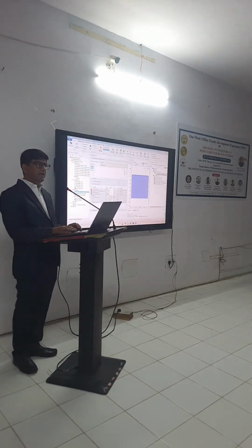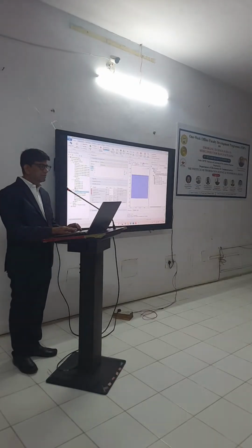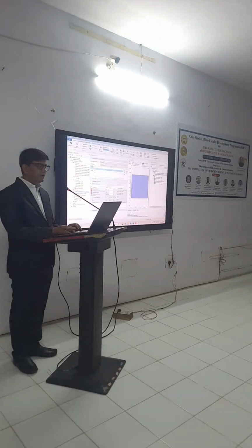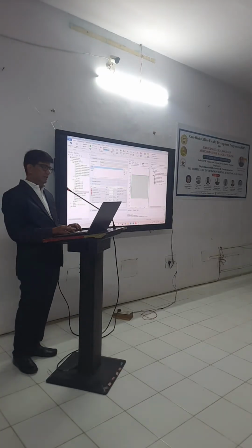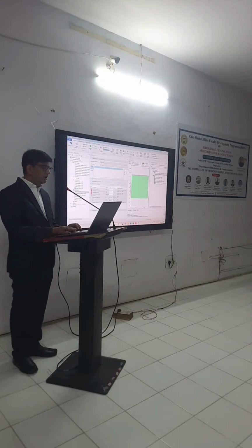What kind of material do I require? This one is my PET, and what about the others? This is not my PET, so I will remove this from here. This is my ZnO layer, so this is not PET, and this is my top electrode, so I will remove it. So I have this as my PET substrate. Then what do I need to do? Again I have to select my next material.